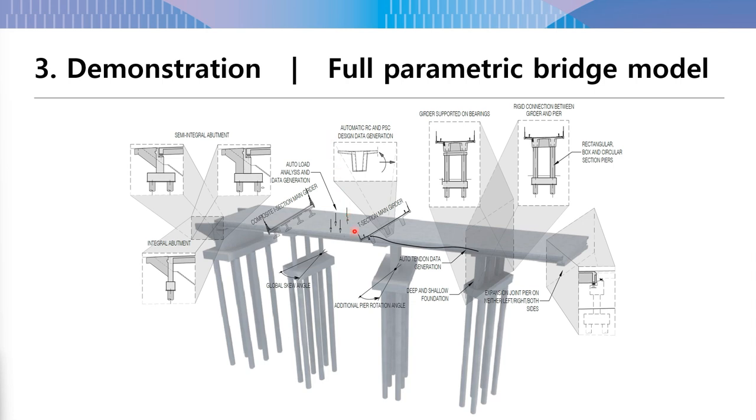Apart from that, there is also a possibility for automatic tendon data generation, in which the user inputs the basic data that is required, for example, eccentricities in span and at piers, and this bridge parametric script automatically enters nodal coordinates for those tendons and prepares input data for MIDAS Civil and MIDAS Civil NX.